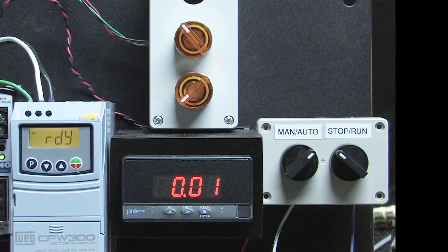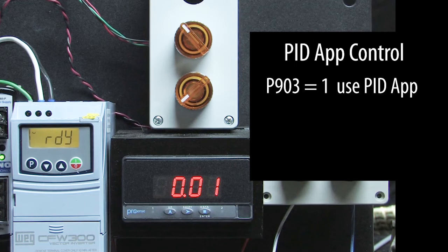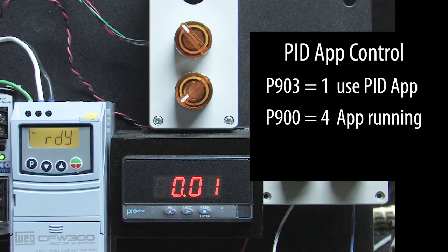Now, one side note. All of this assumes you have the PID app running. You should see a 1 in parameter 903, which says you're using the PID application and not a user application. And you should see a 4 in parameter 900, which says the PID application is running. If it isn't running, then go to parameter 901 and set it to a 1.